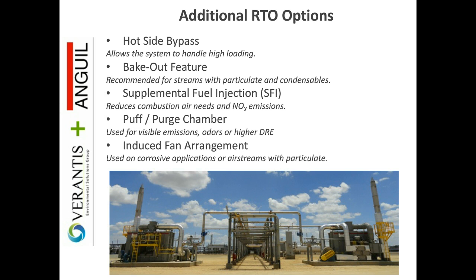What that does is allow us to achieve, rather than say 99% on a standard unit, up to 99.3%. It's also used for odor applications where, if you have a very pungent compound, what you don't want is a small amount of it going out the exhaust stack every 3 minutes. You're looking at potential neighbor complaints. That's where this puff capture system would be used.